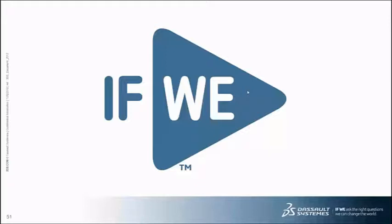In fact, if you take the contact class, there is a slide in that class that talks about the recommendation for using the unsymmetric solver for contact models. So that's one of the first things that I try if someone sends me a contact model that's not converging and it's not using the unsymmetric solver. You just need to eliminate that technical fix before moving on to trying to fix the problem in some other way.